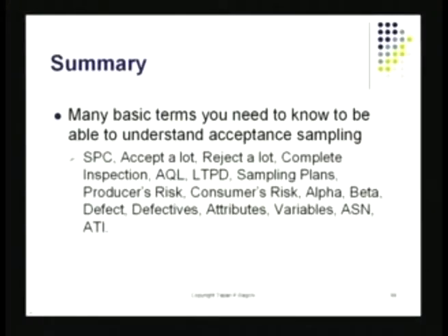There were certain reasons when we would accept the lot, and certain reasons when we would reject the lot. These conditions were given in the acceptance sampling plan as that little letter C. C was the control quantity. Complete inspection could be justified if the item was such that the defect could be critical. It could cause loss of property or loss of life. For example, you'd like to do 100% inspection there.